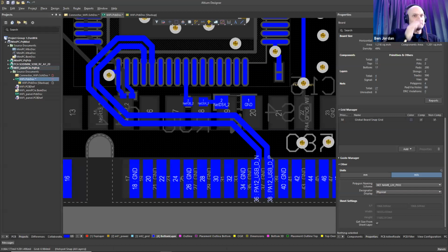And then sort them according to their location. It's just like a spreadsheet view of the net names at that point, and I'd modify each one in the list. That's a much faster way of doing them all, using net labels. So that's just how I would probably attack that problem. And then you have all those names and you can easily add the _P and _N to the right ones.